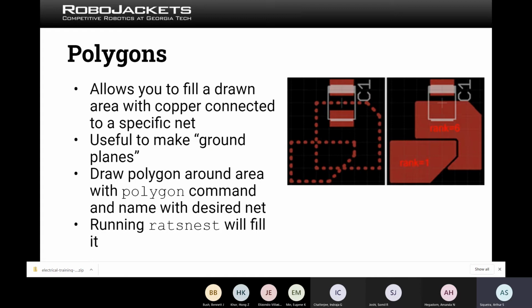They're commonly in the bottom layer for 2-layer boards, where you simply fill out the whole region of your board in one layer with copper, and then that copper will be connected to your ground. So now for any component on your board, you simply pull out a trace a little bit to the right, and then you put a via, and that's it. The via will be connected to the ground because you previously put a ground plane everywhere, and you can easily connect any component to the ground plane.